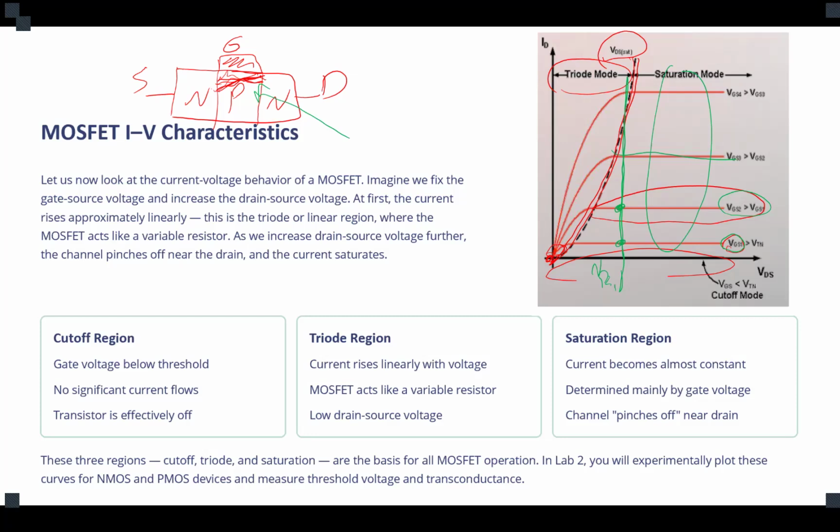Another reason is that when you want to model semiconductors, there is a resistance in the semiconductor which is highly sensitive to temperature. As the semiconductors start working and switching, the temperature goes higher and higher, and probably you see that MOSFETs normally use a heat sink because they get to very high temperatures.